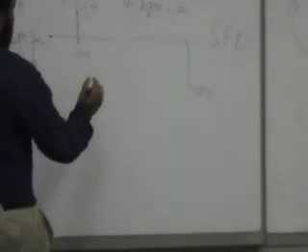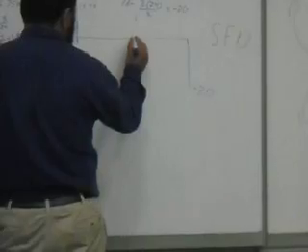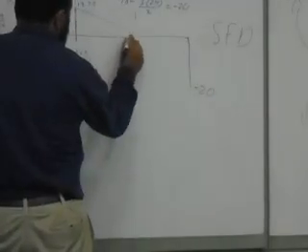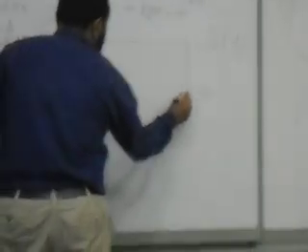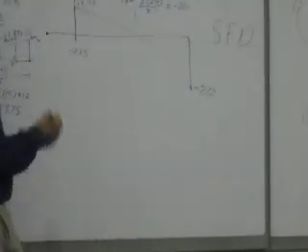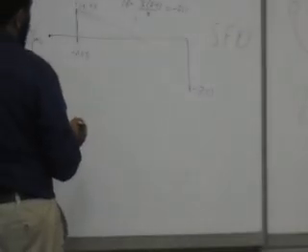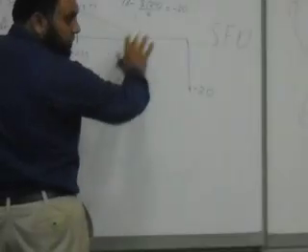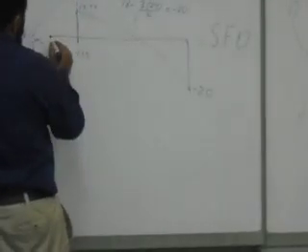Okay, so it's somewhere here. So actually this thing will look like this. This is what this is telling me, in terms of concave. And which makes sense: zero shear is closer to this side. Why? Because the load is larger than this side. So here you're expecting the maximum bending moment to be nearer here. And this is also expected to have a similar behavior, let's say to be concave.